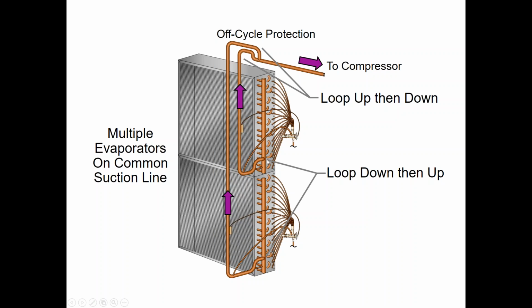Now, this is kind of a self-draining coil. There are other coils with your suction header where your stub out may be at the top, it may be in the middle. And typically those coils will have a drain line down here that will connect to the suction line, which is what you see right here. If you look at that right there, that's an oil drain line. But typically, you'll know that there's an oil drain line if the suction stub out is, like I say, at a middle point or somewhere up higher on the header. So always be conscious of getting the oil out of the coil. Okay, so that's number 1, thinking about suction piping headers.